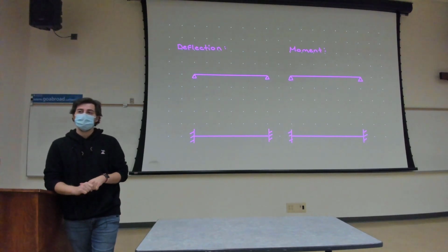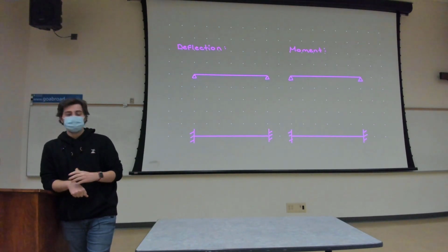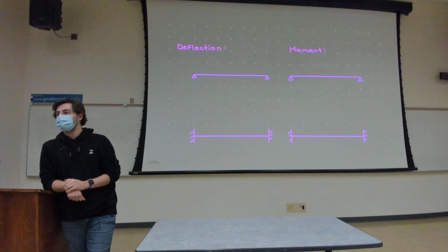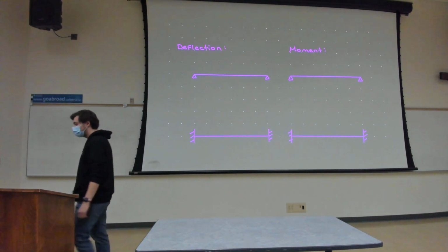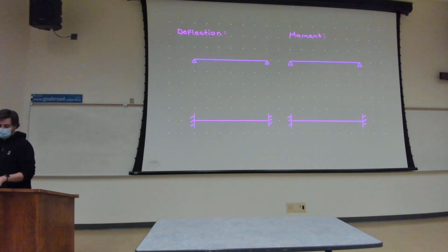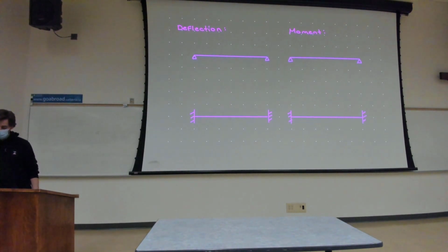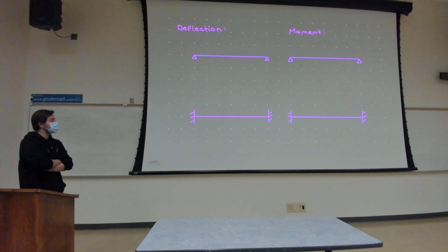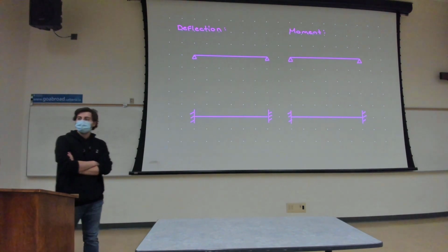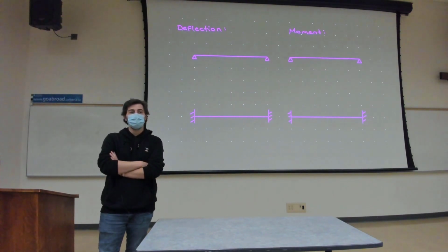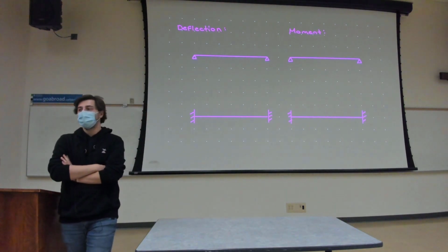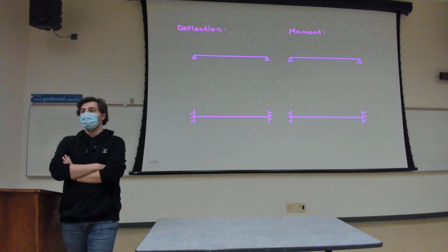Every single beam. The only difference between these beams is, again, the boundary conditions, and those boundary conditions will affect those coefficients. In the assignment, we had 2 different beams: simply supported, and fixed. Now, when it came to the differential equation for beams, how many constants do we have? 4. So that means we need 4 boundary conditions.